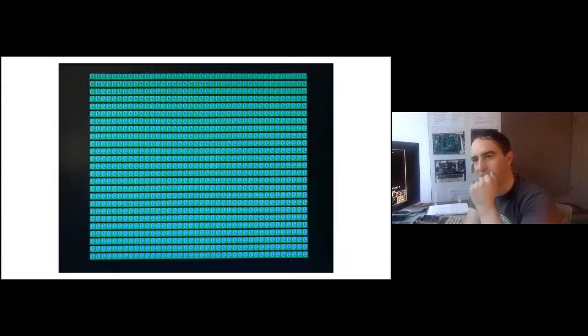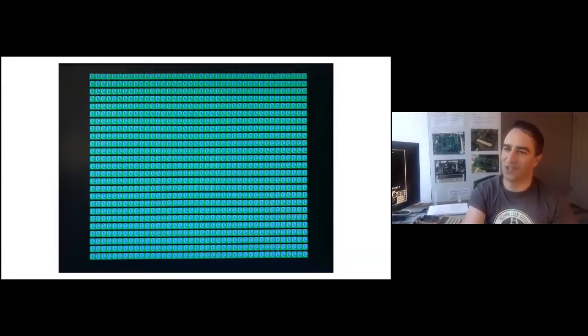the OS used to check for the existence of a ROM in an empty space was instead returning the last byte of the instruction. And so this resulted in the OS thinking that there was a language ROM in position 15 and trying to execute it. And I think the first thing it does is it reads out the title of the ROM and prints it. And so I guess this resulted in a never-ending string of ats.